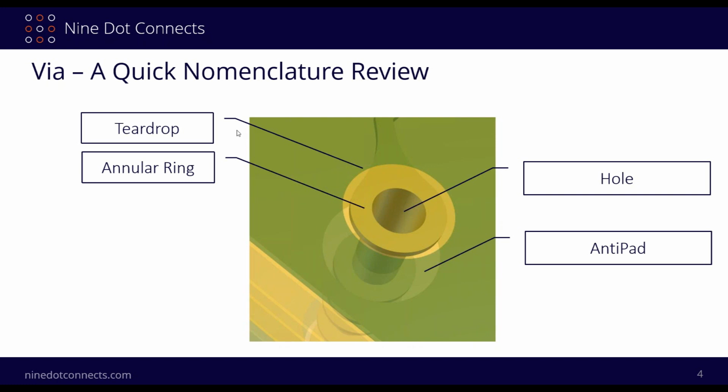And by the way, Altium Designer, and I know also Allegro, has the teardrop as well. What's the idea of the teardrop? So if you've got a trace that is coming into the annular ring here, it's always nice to provide a little extra copper here onto the sides. Again, as I'm going to mention here later on, this hole is never dead center, and so it gives a little bit more of a target to hit. So using the teardrop certainly is no disadvantage, and I encourage you to use it. But it's usually kind of a post-process. You first route, and then later on, you run the teardropping function.